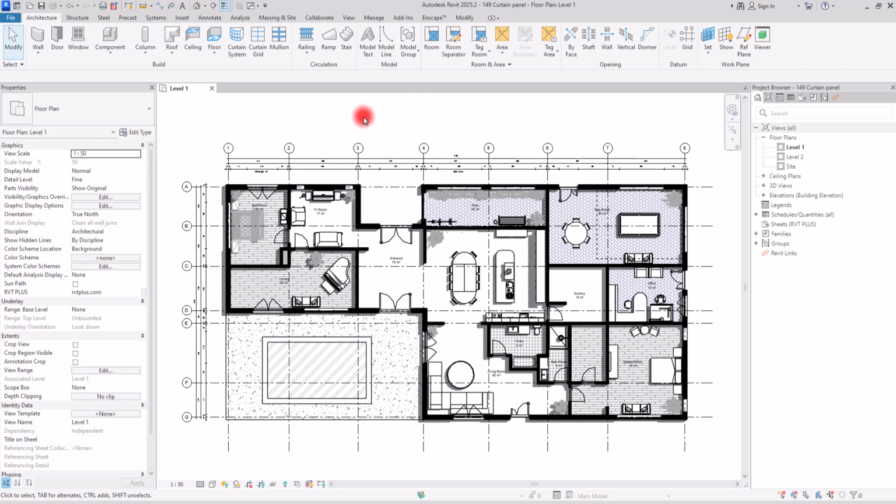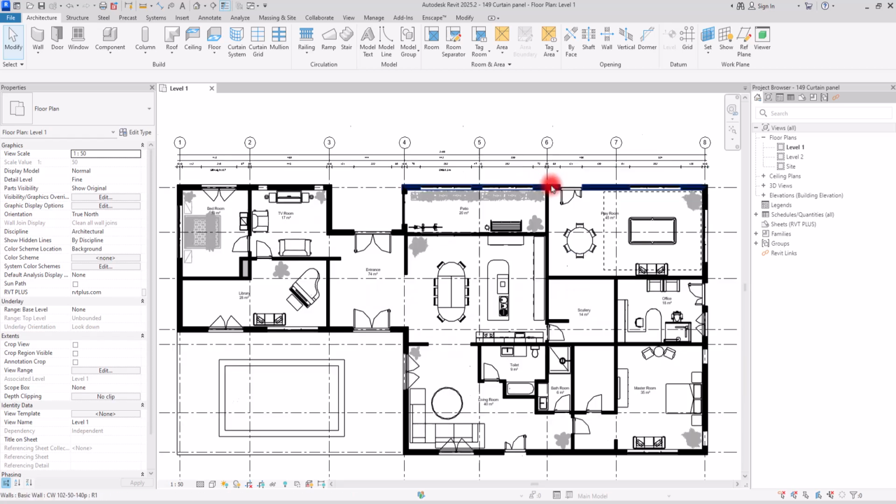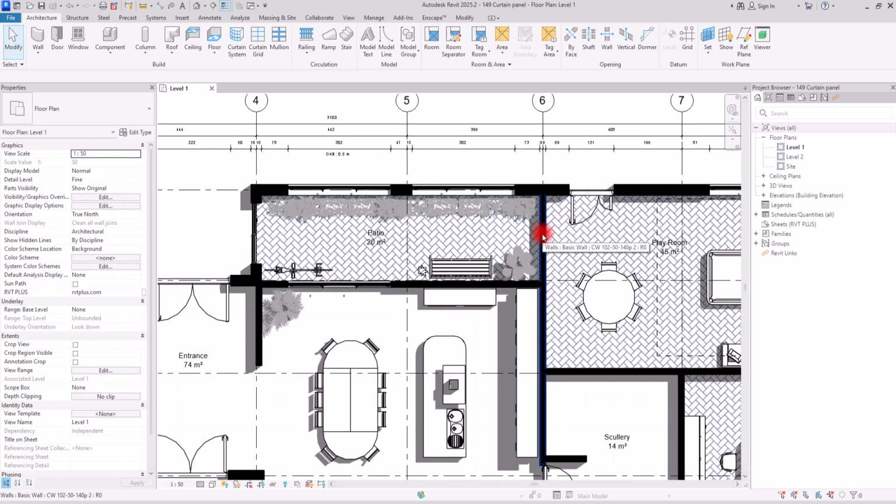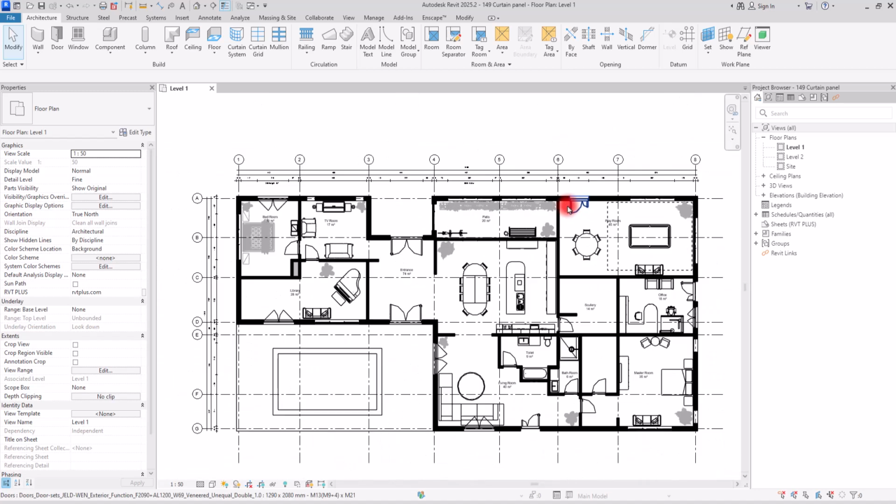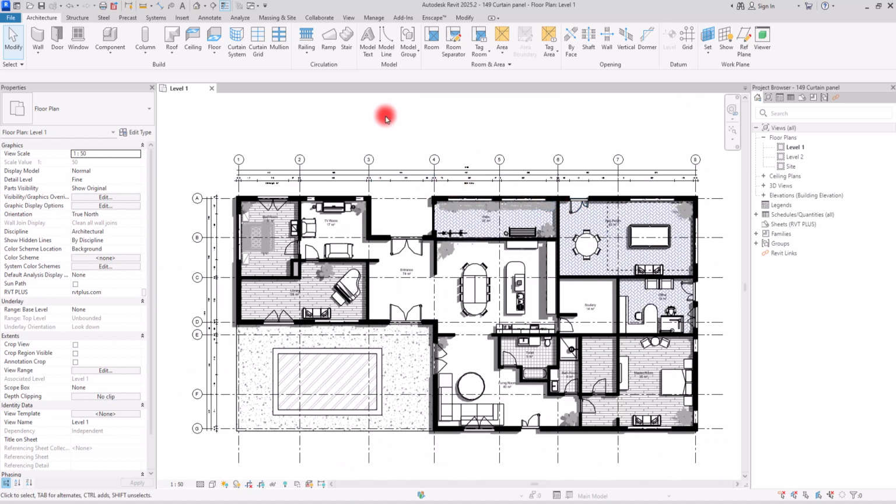In almost all of the project, for some parts, we need to add more detail. In some parts, we need to add more information. For example, in this 2D plan, maybe you want to add information about this corner, about the connection, about the way that your walls are connected together. Or maybe in your section, you need to add detail about the connection between your wall and your roof. Or maybe you have a very complex design and you need to add extra detail for those sections. In these cases, what we can do is to add a callout.